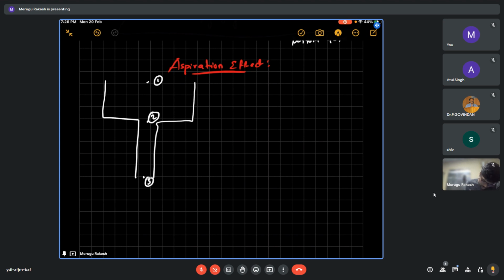One is at the atmosphere, two is at the junction of the pouring basin and the sprue, and third is the junction to the ingate, that is the sprue bottom area. Now, we take P3 to be atmospheric, which ensures that all the above pressures will be atmospheric, or even more than atmospheric is fine.